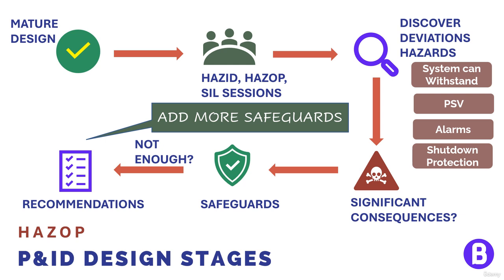That's why it's expected that after HAZOP is carried out, we shall update the P&IDs to reflect its outcome. This can be another design issue considering the HAZOP outcome, so the design issue may be reissued again in order to consider this HAZOP outcome, or it can be considered a construction issue. So at the end, we can update this in the construction issue.